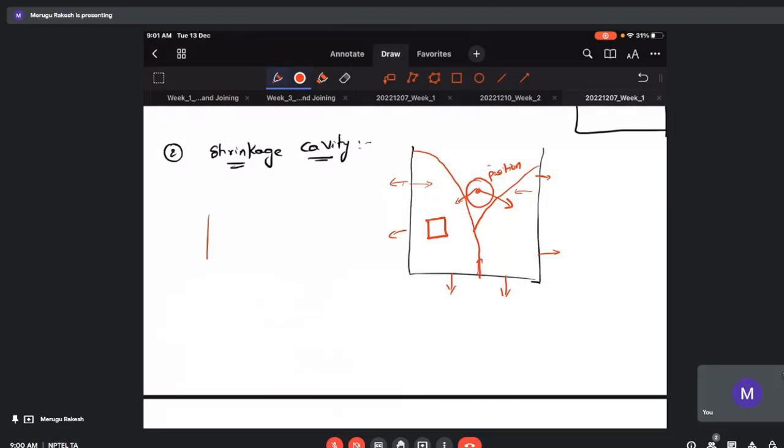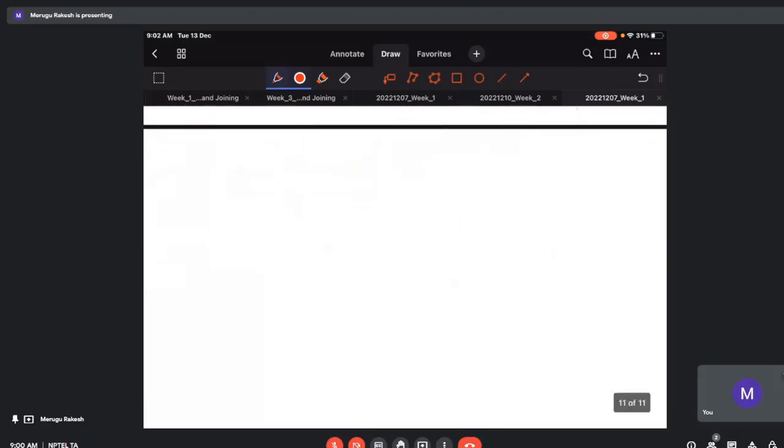But inside the casting, you can clearly see the distinction between gas porosity, which is more or less spherical, whereas shrinkage cavities are very rough, flat cavities. This is due to improper gating and risering systems. If we can provide extra material using some riser, which will compensate this loss, then we can avoid this defect very easily. So next, let us move into the hot cracks or tears.